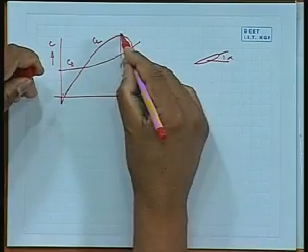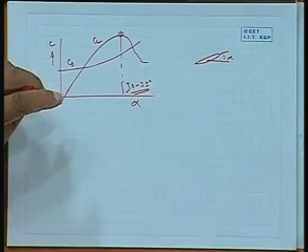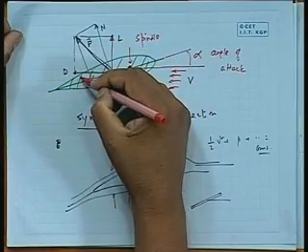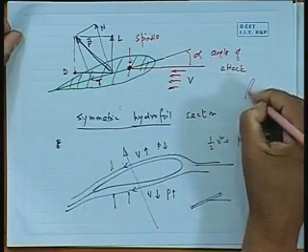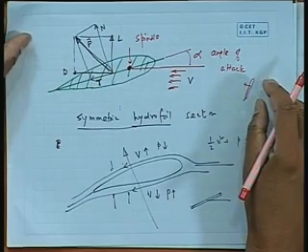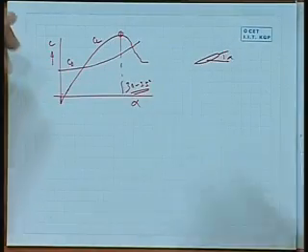Typically this is exactly why in fact you do not have the rudder angle more than 30 to 35 degrees, because your idea is to get lift. There is no point of not getting lift and getting only drag. If you have a rudder like that, you are getting no lift force but only drag force, there is no point. You basically want the lift force more. In fact, you want as much lift with as low drag, that is your ambition.